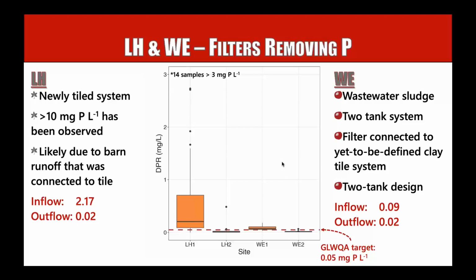As the sites within that media become saturated with phosphorus, we would expect that the efficiency might go down and our outflow concentrations might creep up a little bit. That's another thing we have to monitor about these designs as well. But right now they're working very well. No clogging, and we're getting really good phosphorus reductions here.